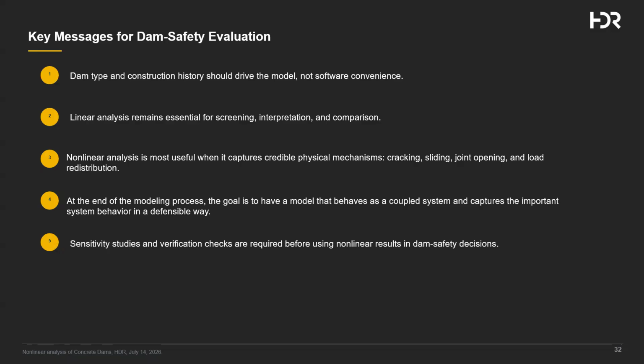The key messages here are that the dam type and construction history should drive the model, not software convenience. Linear analysis remains essential for screening, interpretation, and comparison. Nonlinear analysis is most useful when it captures physical mechanisms, including cracking, sliding, joint opening, and load redistribution.